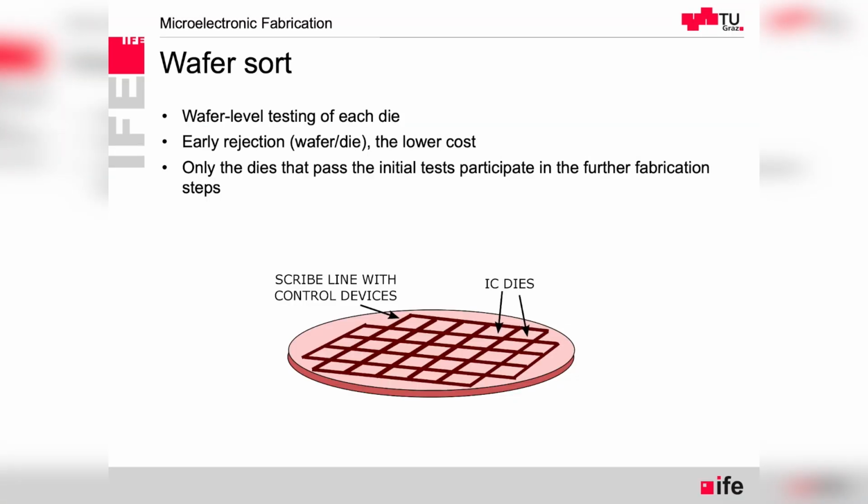So where we have finished, we have processed the MOSFET transistors, different devices. There can be also resistors, capacitances, even inductances, whatever we need for analog mixed signal circuits, memories, and all those blocks, metallization. And everything is made on one wafer after a huge number of process steps. Next thing is we have to make it ready for selling to the customer and putting into the product. So it has to be properly tested, it has to be packaged. And all those things are now called the backend.